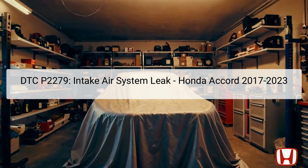DTC P2279 refers to an intake air system leak identified in Honda Accords from 2017 to 2023. This Diagnostic Trouble Code indicates that there is an issue with the intake air system that can affect engine performance and fuel efficiency. Understanding this error code is crucial as it can lead to potentially significant problems, including poor acceleration, increased emissions, and an overall compromised driving experience.